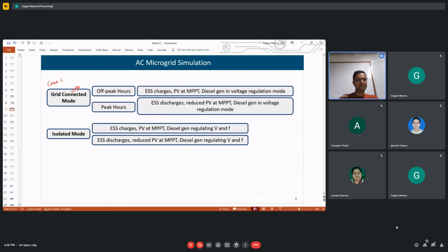These are the representations of the different kinds of voltage power quality issues. First, these are voltage related issues. Here we can see the normal, good voltage, and this is the sag, where there is a reduction in the RMS voltage for a few cycles. There is a guideline for how many cycles it must continue to be called a voltage sag.